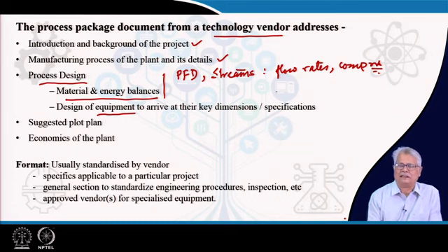You will have the process flow diagram naturally with the stream flows and the compositions as well as the energy flow requirements, a process description of the different units which are involved in your plant, and you will certainly have the process and instrumentation diagram, which will tell you what the control loops and the process parameter indication loops are. That means, again in industrial parlance, you can look at it and find out what the open loops and the closed loops involved in your plant are.